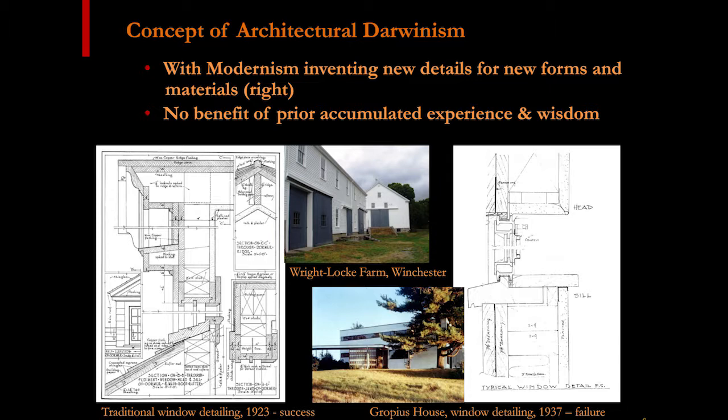Of course, there were no plans or no architect on this, but I think this plate from Traditional Building Materials, 1923, Philip Knobloch, is a great book. I've got some suggested reading on my handout, and that's in there. It shows basically that this was figured out. We knew how to do wood-framed clapboard buildings. We knew how to do doghouse dormers. And I could spend a whole hour talking about how thoughtful all these details are at the micro level, just the way everything overlaps, the drip edges, the flashings, the underlayment, everything about it is incredibly well thought out, and you would do very well to build a building just like this today. They really had it down.